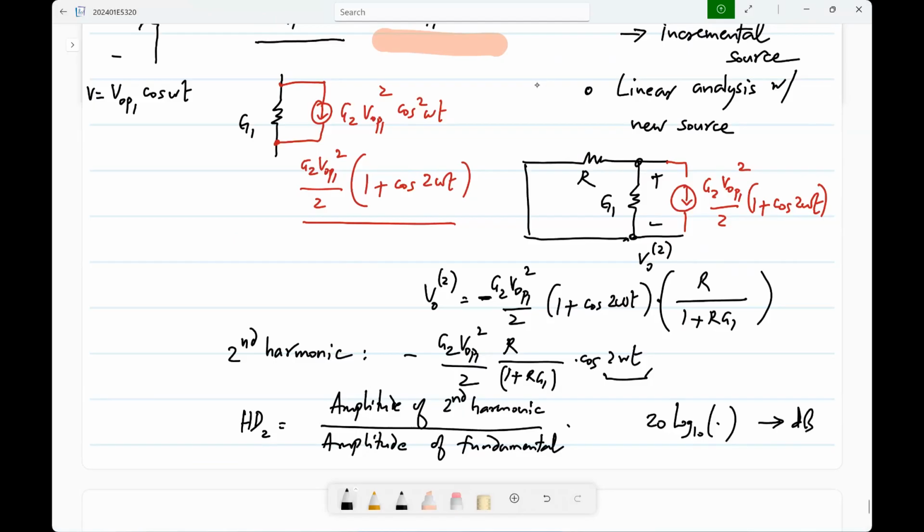So again, basically the one thing that you need to know for a career in circuit design is linear circuit analysis. If you know that, everything will reduce to linear circuit analysis. We won't analyze something more complicated than that because it's actually too difficult. Well, our goal is to get insights into circuit design, but you can see that distortion analysis, noise analysis, mismatch analysis, all of them are about the same. With every element, you will get some additional source, and with that additional source, you have to be able to carry out the analysis. Okay. Any questions so far?